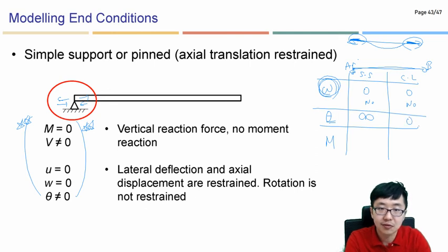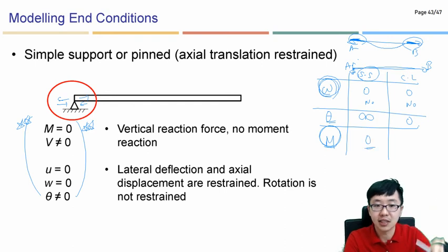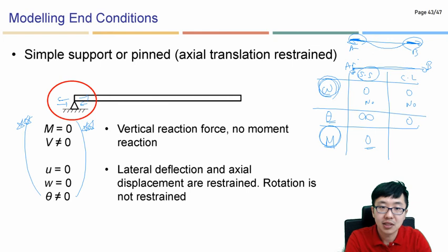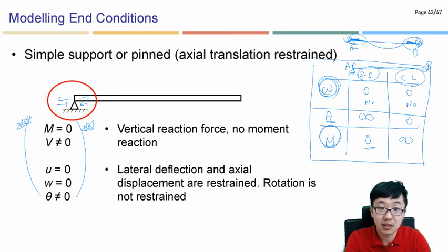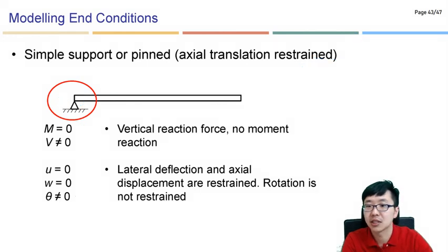So it is 0 at A and B. In the case of moment, because in the case of simply supported case, moment must be 0, which means that moment free at the end. But here, clamped condition, they hold it restrained, so maximum moment will be applied. So this is important. We will utilize this in topic 11 for our derivation part.